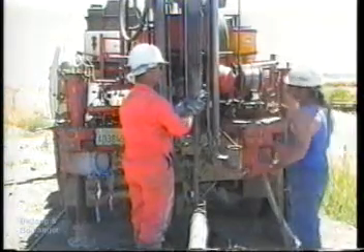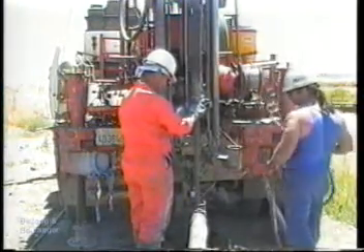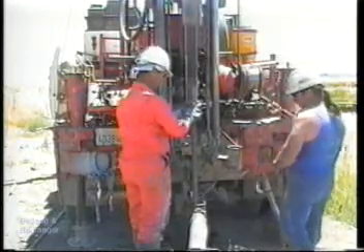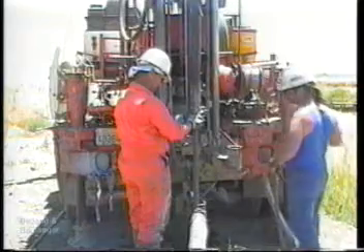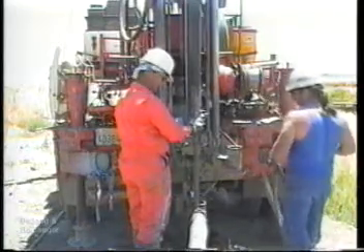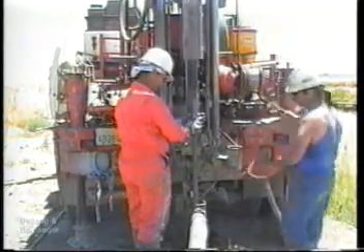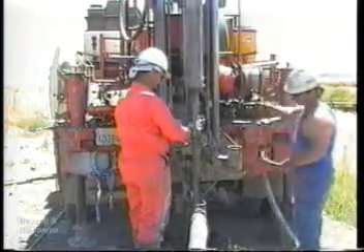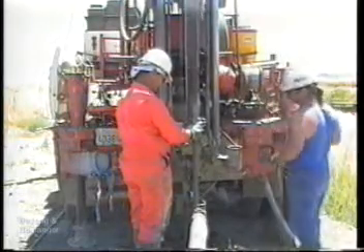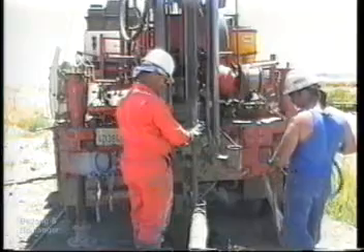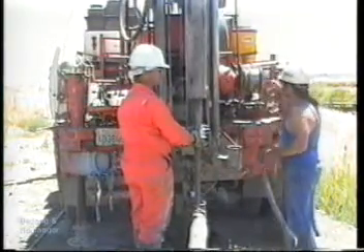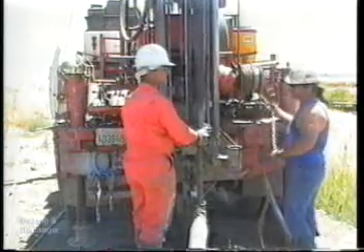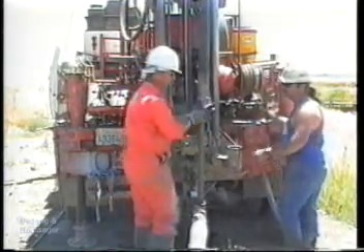Penetration Test, or SPT. This test consists of counting the number of blows of the hammer required to drive the split spoon sampler a specified distance into the ground. The essential features of the SPT test include a drop hammer weighing 140 pounds, falling through a height of 30 inches onto an anvil at the top of the drill rods, and a split spoon having an external diameter of 2 inches and an internal diameter of 1 3/8 inches, and a length between 18 and 30 inches.